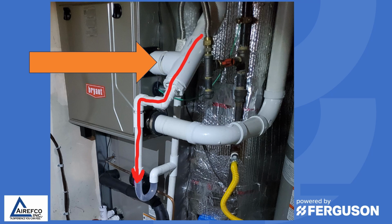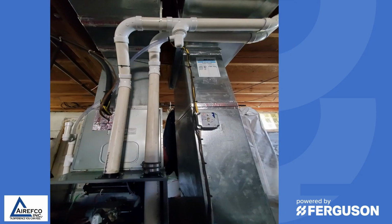In some environments, this is necessary as condensation builds up on the intake to the furnace. Here's another example of a trap being put in the combustion air pipe, taking the condensation out of the combustion air pipe before it reaches the furnace. These methods are perfectly fine on the combustion air side, but when you put a trap in the vent side, that's when you might get into some problems with carbon monoxide poisoning.